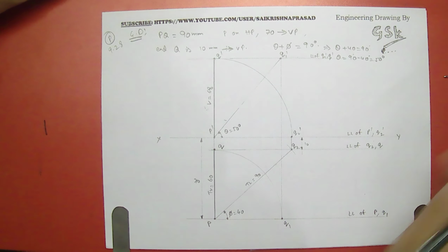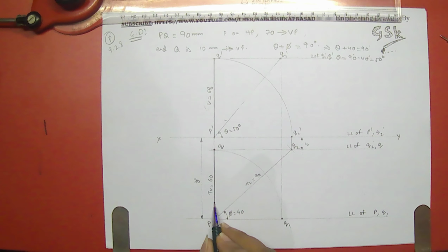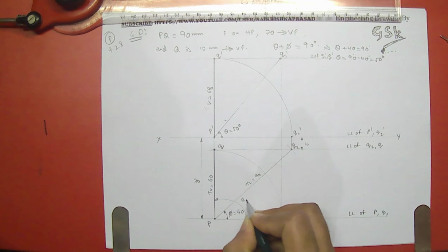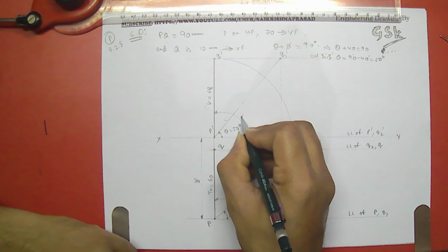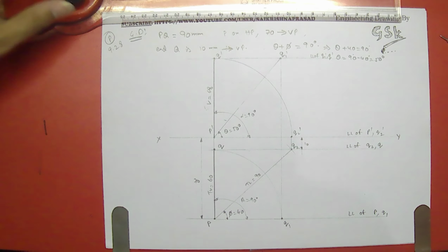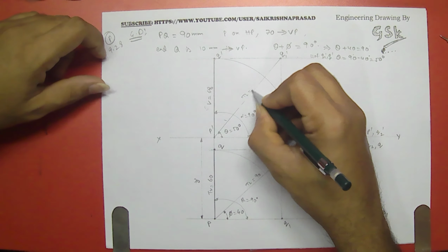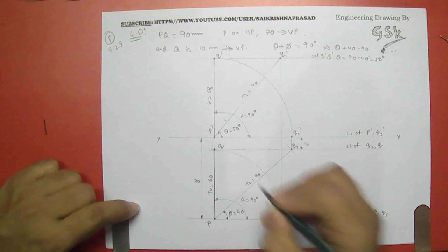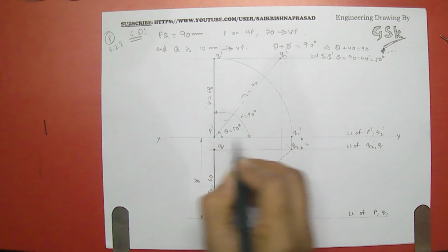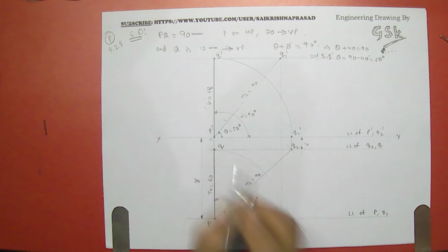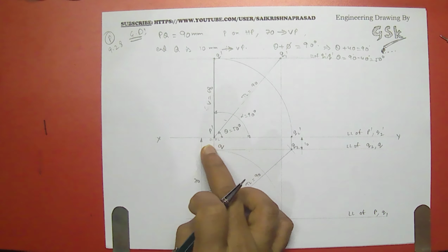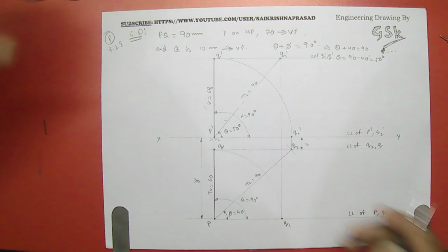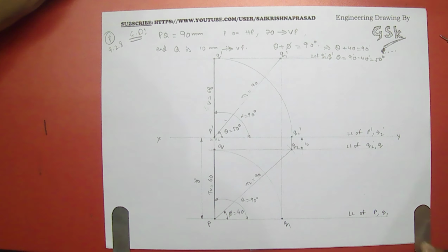Now we have to find alpha and beta. So here you can see this is 90 degrees. Beta is equal to 90 degrees, and alpha is equal to 90 degrees, the angle, right? So this is true length 90, this is true length 90, and this is the distance between O1 and O2. Because it is coming down to this, we won't be getting any distance between O1 and O2. O1 and O2 is 0 for this point. Okay. By this we are going to finish the problem.